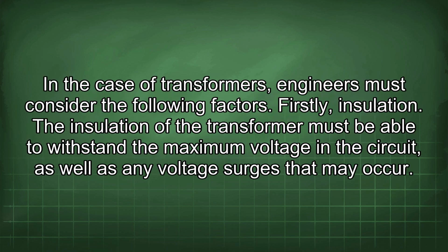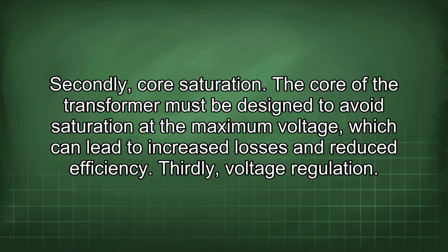In the case of transformers, engineers must consider the following factors. Firstly, insulation. The insulation of the transformer must be able to withstand the maximum voltage in the circuit, as well as any voltage surges that may occur. Secondly, core saturation. The core of the transformer must be designed to avoid saturation at the maximum voltage, which can lead to increased losses and reduced efficiency.